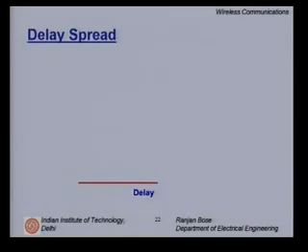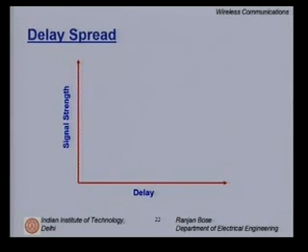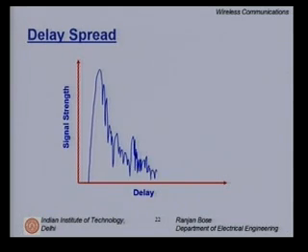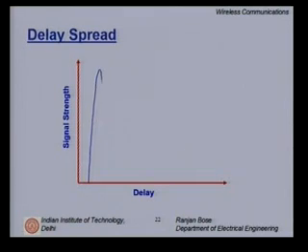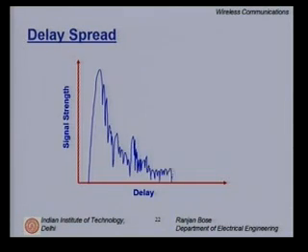So, let us see graphically what happens. On the x-axis, let me plot the delay. This could be described as an outcome of an experiment where a signal is transmitted, maybe a pulse, and I am trying to look at an oscilloscope at what I receive back. On the x-axis is the time axis, which has a measure of delay. On the y-axis, we plot the signal strength. So, what I get is something like this on an oscilloscope. It's a refreshing oscilloscope, so you see it 2 times.